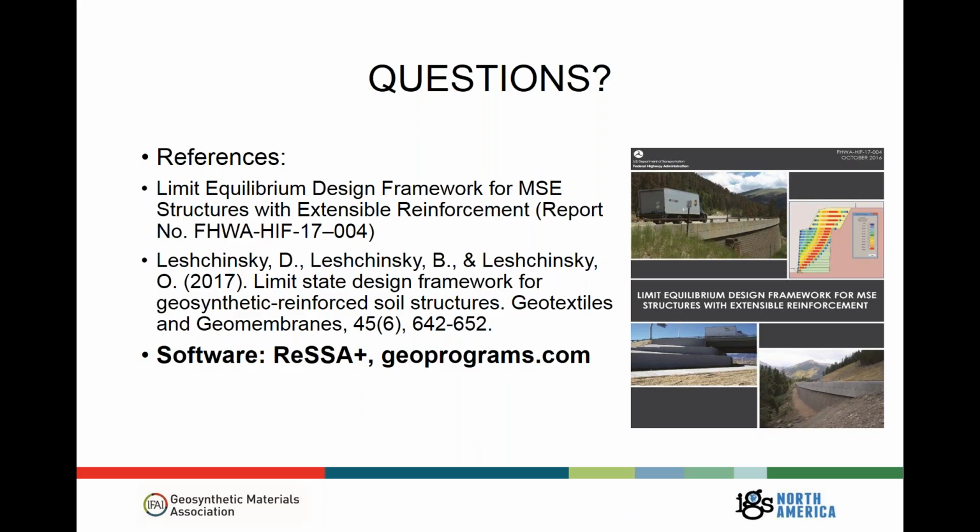Yeah, I don't have an answer to that, but I'd be happy to at least send some references that describe the corner problem. Basically, if you have a corner angle, 90 degrees being a right angle for a corner and 180 being a continuous plane strain wall, you will start to see basically degeneration into plane strain conditions as you approach 180 degrees. But the problem is that it's still rather 3D up until that point.